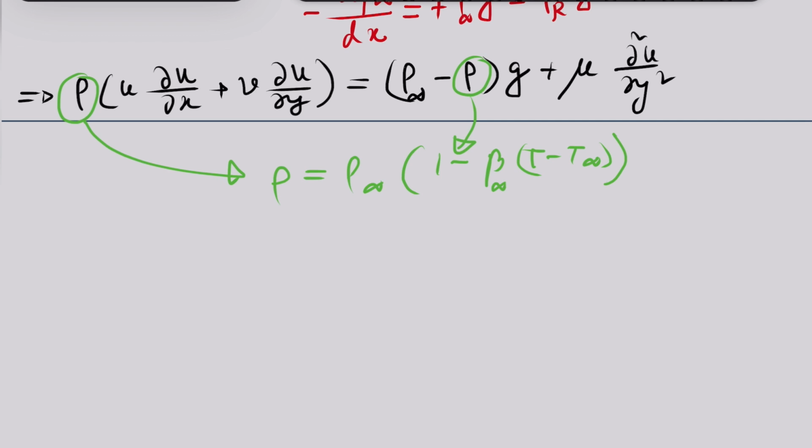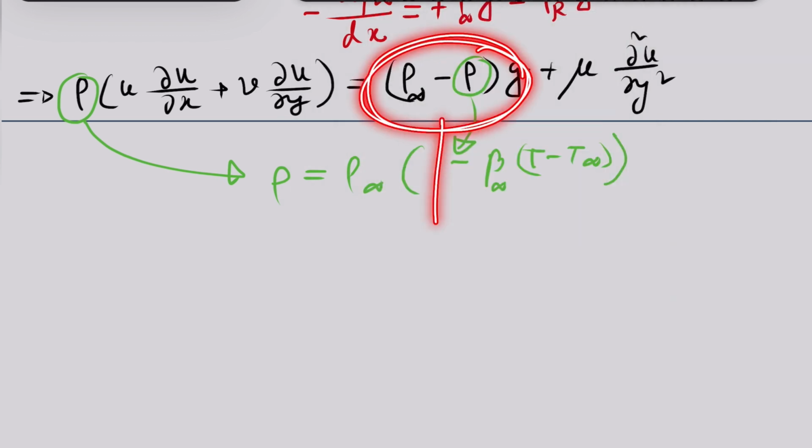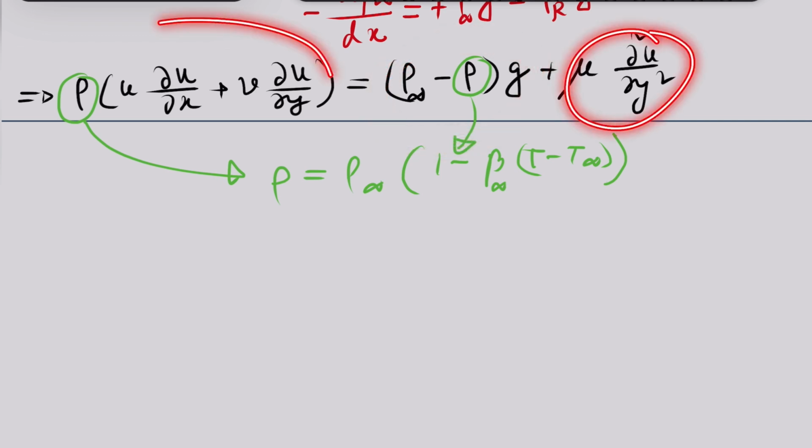That is why our dear scientist Boussinesq put the approximation that, my friend, because it is natural convection, we have to keep this term, because this is the term that is driving the flow, and loosely we call this a buoyancy force per unit volume, because all these terms have the units of force per unit volume.